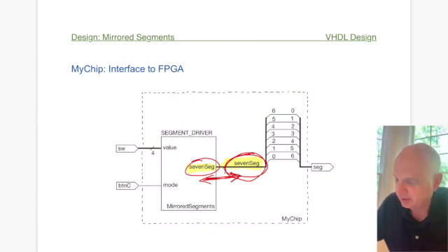So the big thing here is we're swapping bits, and there's a lot of different ways to do this. You can do this in a process, which we'll see later. We can do stuff with for loops, but for something so simple as these 6 lines, it makes very little sense to do anything super complicated and run the risk of having an error. You've only got 6 lines, so just write it out. Put 6 lines in there in your VHDL code and make it so.